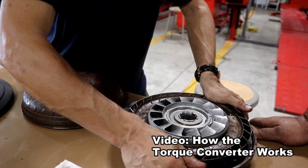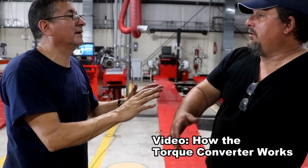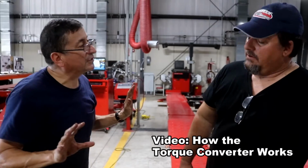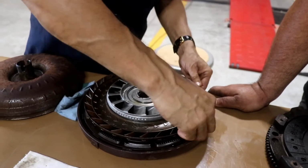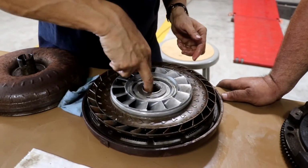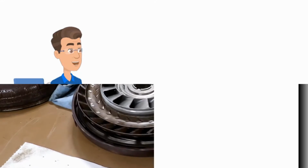So it's all due to hydraulic pressure. With the centrifugal force of the converter forcing that pressure, causing it to engage. Correct, it's basically centrifugal force. And now this one is engaged with this, and the input shaft of the transmission is connected with this. Right now, the input shaft of the transmission is spinning at the same speed as the flywheel. That's it.